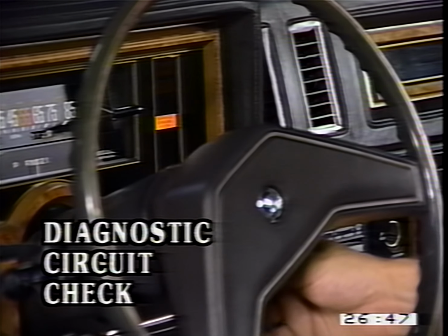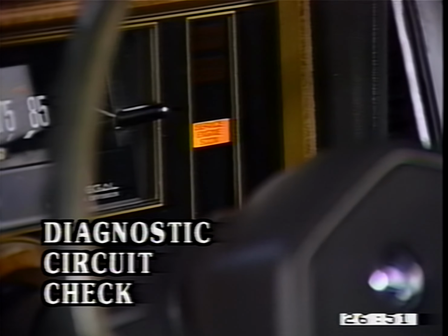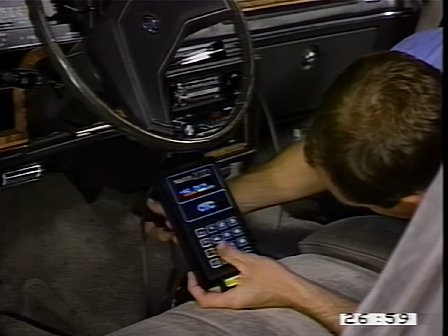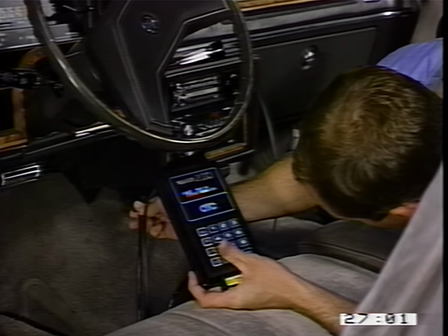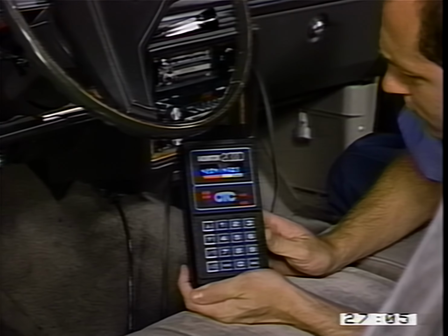The diagnostic circuit check is a 3-step procedure, including checking the operation of the service engine soon light. This is a key-on, key-off type of test. The second step is the grounding of the test terminal to determine if there are trouble codes stored, or connecting a scan tool for the extracting of codes.